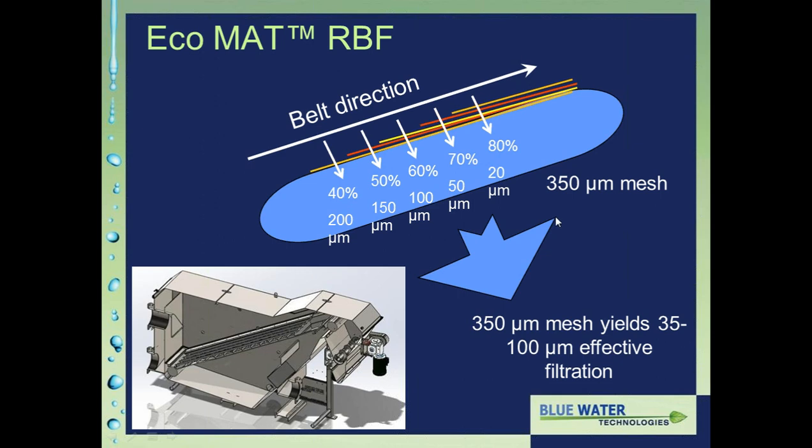Typically we're looking at like a 300 to 350 micron mesh for sewage applications, but when we're talking about stormwater and overflow scenarios, we want to tighten up that micron pore size. And that reasoning will become apparent as I continue through this discussion. But we typically go down to between 100 and 150 micron mesh for those applications where stormwater mitigation is important, because again, that enables us to have a higher capture rate. And the reasoning is behind the mechanism for removal here.